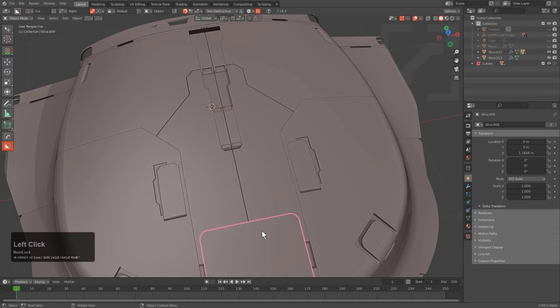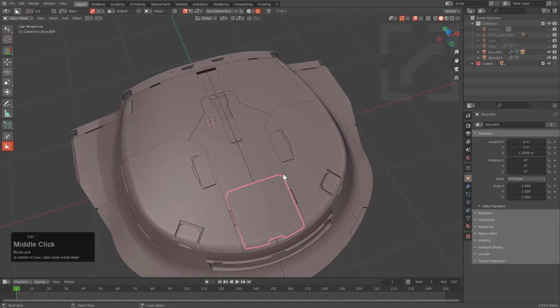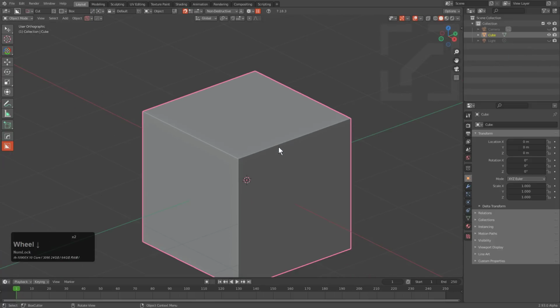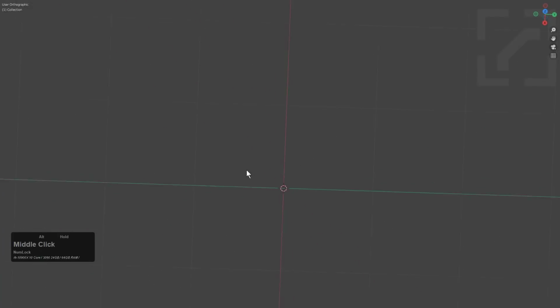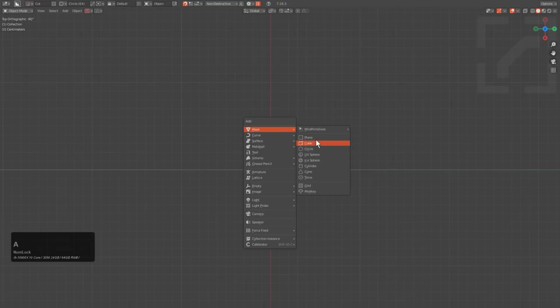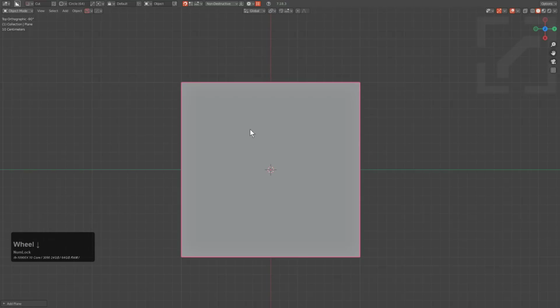So holding control in order to statically keep the dots is something that I found to be a little bit of an interesting curiosity. However, another example I want to show is that if we press control N and make a new file, I'll just delete this cube, press control shift spacebar to go full screen, and we'll just shift A at our plane, alt V wireframe, and we just want to switch over to box, shift X. And I just want to show another interesting thing about static grid at this time, and that is the face fill capabilities that it has at this time.